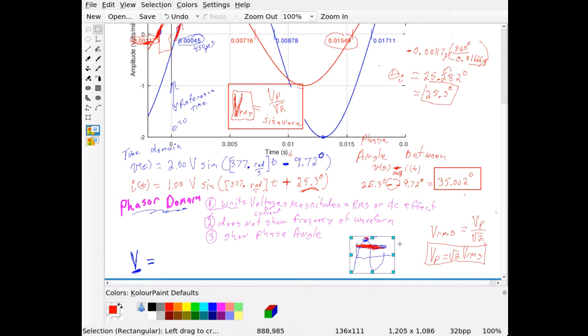So I always use that as a guideline, but I just didn't stop and double check as I wrote it. You're only at the peak value for a very brief amount of time. So the RMS value must be less, so you do the divide. To go from peak to RMS, you're dividing because it needs to be smaller. To go from RMS to peak, that's when you multiply.